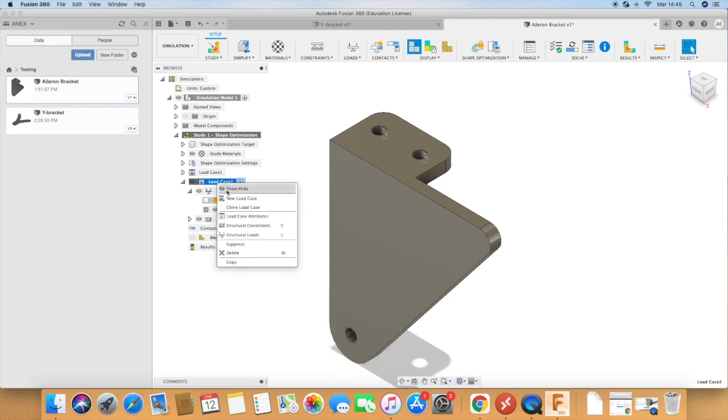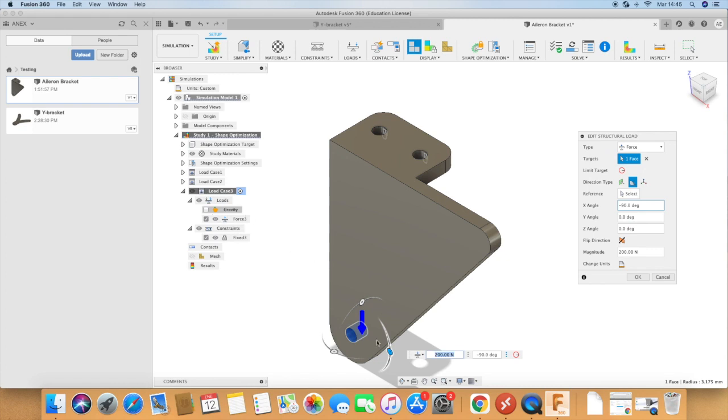I'm gonna clone load case. Boom. You need to click on that little hole so that the software knows that we're using it. We're looking at that load case. We go back and loads. The constraint is the same, by the way. Yeah, we're kind of neglecting gravity. Boom.